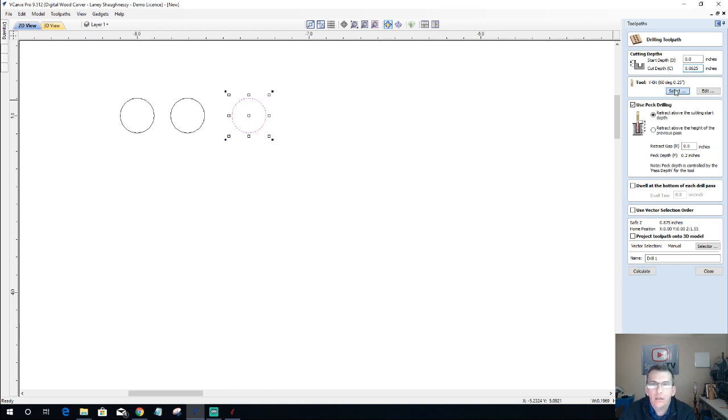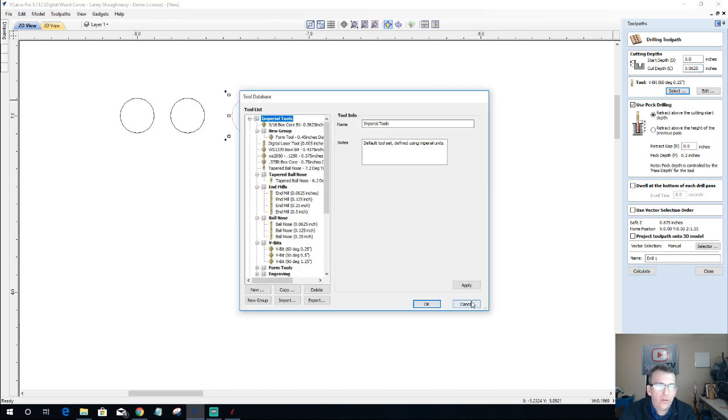Now, with any end mill, you're going to be able to use whatever size. But if it's a drilling operation, you definitely want a 5 millimeter drill bit, because the drilling operation is not like a pocket cut. When that bit comes down, it's drilling a hole, just like a drill bit. It's not moving around to make that hole bigger. It's just drilling down. So if I'm using a 1/4 inch bit, I'm not making a 5 millimeter hole. You know what I mean? So you need the appropriately sized bit for that.